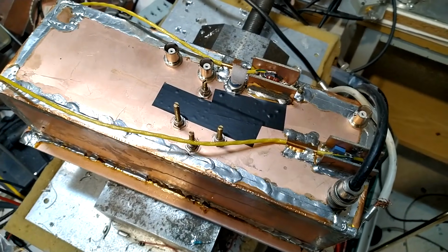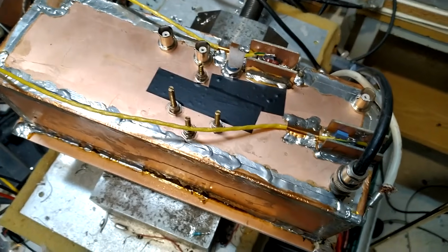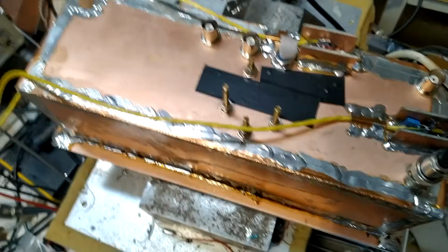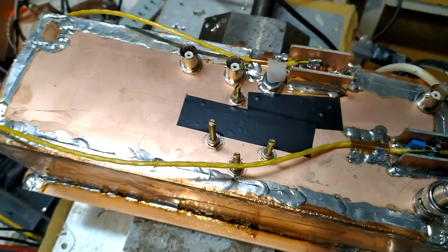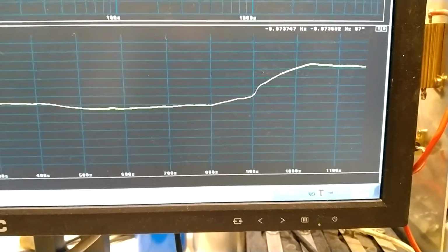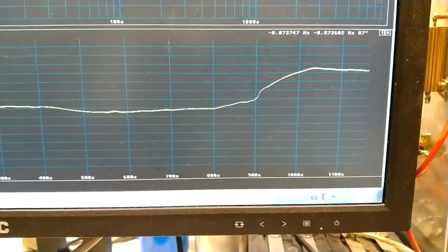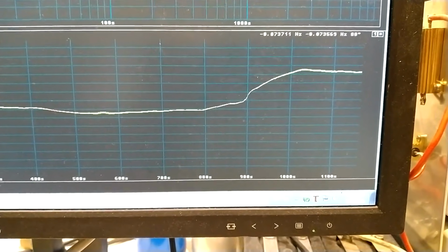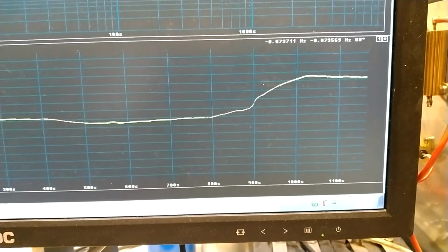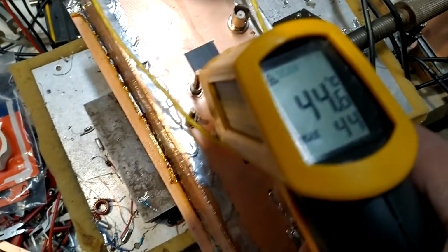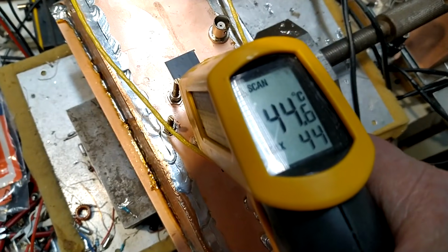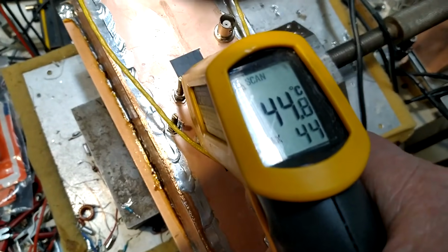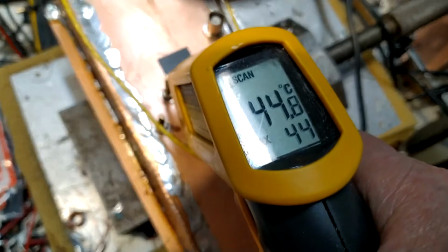Measurement has been running for a long time with this box. Now I put these 2 pieces of black tape on the box, in order to be able to measure the temperature. The black tape has caused the temperature to drop a little with an associated frequency change of 8 millihertz. The highest temperature I can find is 44.6 degrees with this infrared radiation thermometer.